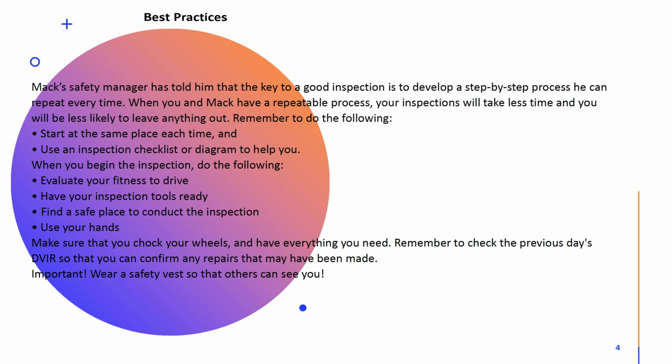Use your hands. Make sure that you chock your wheels and have everything you need. Remember to check the previous day's DVIR so that you can confirm any repairs that may have been made. Important: wear a safety vest so that others can see you.